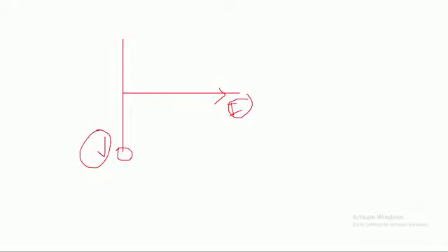If we are having this kind of response from the unknown element, when you are applying the constant current and calculating the voltage drop across it, and you are putting those two values on the phasor diagram, with current at this position and voltage at this position, then I can say that the current is the leading factor and voltage is the lagging factor. Or I can comment that current is leading the voltage, or voltage is lagging the current.